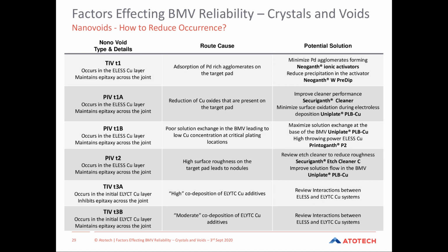Moving into the additive co-deposition defects, really this is a very case-by-case event. There are certain electroless baths we found are compatible more with other electrolytic baths and vice versa. So it has to be done hand in hand to look at the additive deposition and potentially also the impacts of that with the electrolytic baths as well.